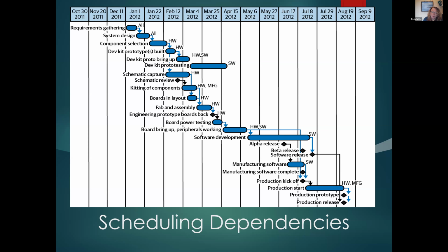For example, I worked on one project where we were supposed to have external memory to help with updating firmware in the field. When the external memory got flipped around in the hardware manufacturing, they couldn't fix the boards that had already been manufactured. So we did firmware updates in a way that was much more dangerous to the system if it was powered off. And we didn't have much time to test the new loading mechanism because we didn't know we needed it until we got the boards back and the memory didn't work. The project worked out, but I still cringe when I think about that code and the chances we took, the risks we added because the hardware didn't come up the right way.